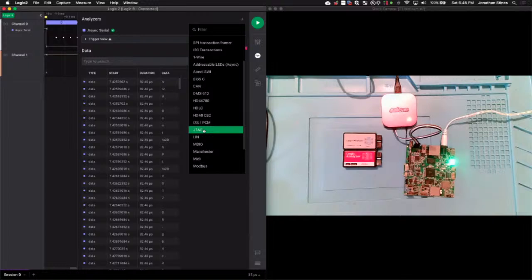Now, for JTAG, say for instance, you don't know what the pinouts are and you're trying to identify that. For me personally, I would go after a multimeter first, and I would try to ring it out with the MCU. I would try to find the data sheet and use that data sheet to identify where on the MCU those pins fall out, and use that to identify the pinouts of the JTAG. If you don't have the data sheet, or maybe you don't know where the MCU is, or maybe it's a BGA MCU, then you'd maybe use some type of boundary scanner.